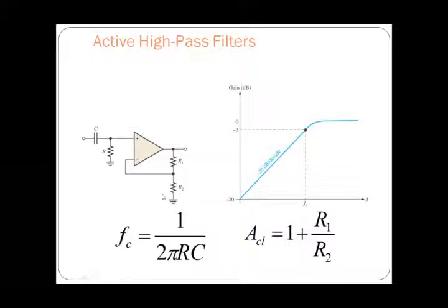So what happens to this feedback when I am going to introduce this feedback? Here I am going to use an op-amp, and you can observe that the input is given to the non-inverting terminal. Then this op-amp is going to act as a non-inverting amplifier. As we know, the gain of a non-inverting amplifier is nothing but 1 plus RF by R1.